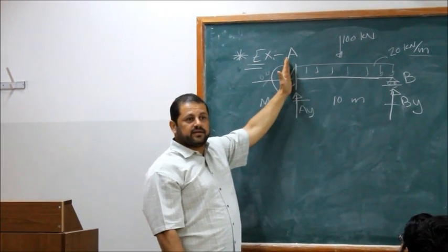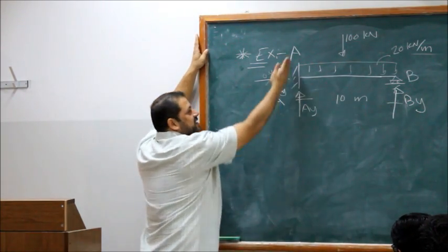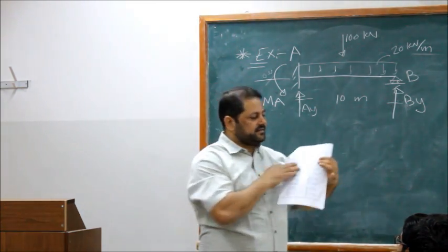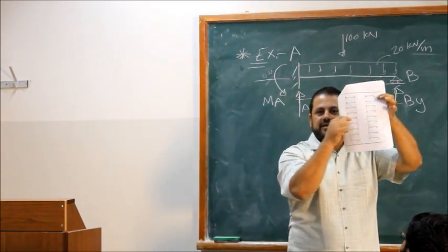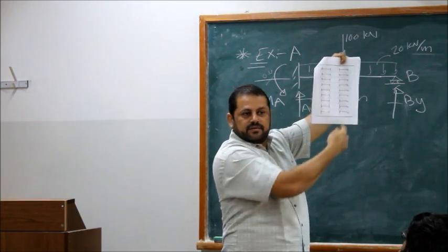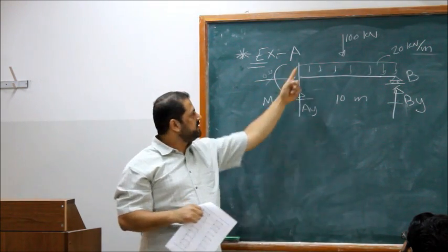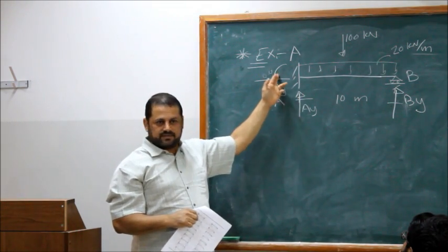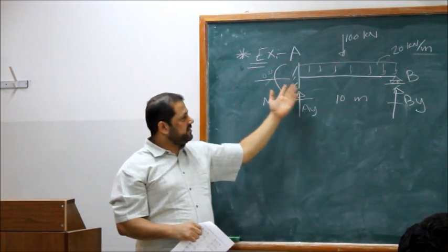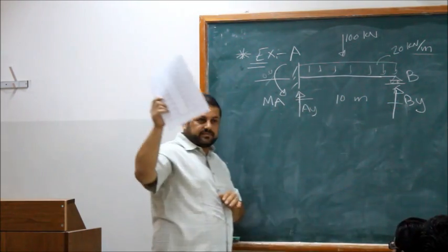So the moment here is the fixed end moment. MAB is the fixed end moment at A. What is the sheet? W. Direct from the right hand side, direct. You have it, it's given. And once you have something like this, you don't have to go with the equation. This is given to you directly, go for it. So you calculate M, then you find those two.